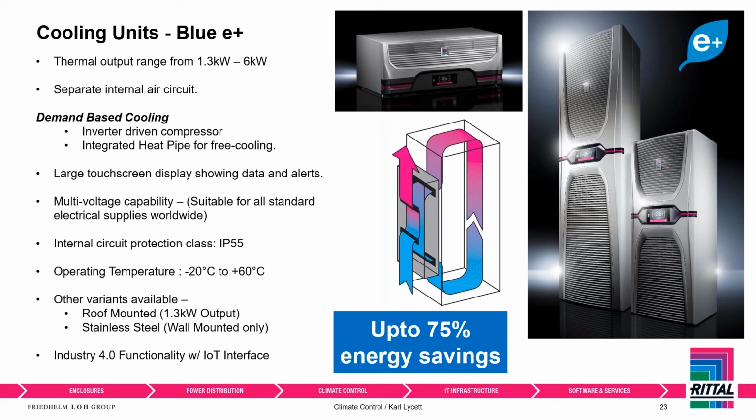So the refrigerant circuit in the Blue E Plus cooling units is inverter driven, the compressor, etc., and the fans are all inverter driven, so we can have infinitesimal modifications of the output. So we can be working at 66% rather than 100%. Things like that. And the other great thing is, as I mentioned, we've got this heat pipe. Now, the heat pipe works like an air-to-air heat exchanger and doesn't require any electricity. So what that means to you is, when it's cold outside, or when it's winter, the unit will go, hang on, it's cold enough outside that I can turn my compressor circuit fully off.